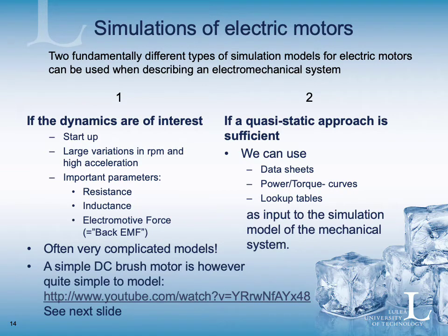But often we don't really care that much about the dynamics. We have some type of quasi-static approach, and that's sufficient. If you are not interested in exactly how it works with the fast acceleration and so on, we want to monitor energy consumption over a longer time or something like that, then we can instead use data sheets, power or torque curves, or lookup tables as input to the simulation model of your mechanical system.